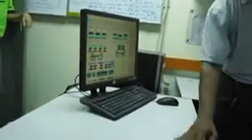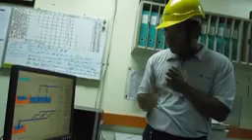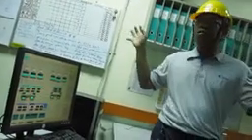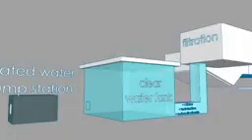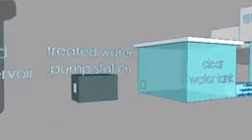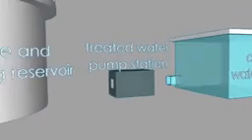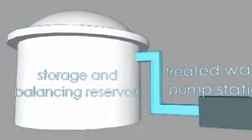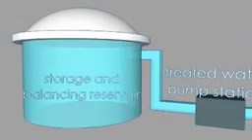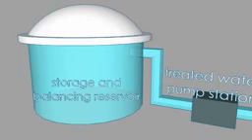Nowadays, the water treatment plant is automatically synced with a computerized controller, which makes the task easier for the observation of water level, raw water intake and disinfection process through programmable systems. From the clear water tank at the water treatment plant, treated water is pumped through long pipelines to balancing reservoirs with sufficient height for distribution by gravity to service reservoirs in various demand centers.